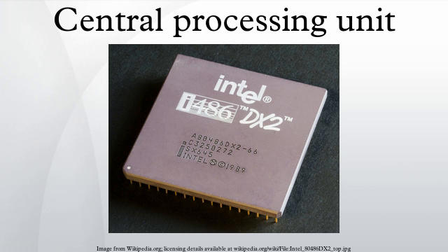In more complex CPUs than the one described here, multiple instructions can be fetched, decoded, and executed simultaneously. This section describes what is generally referred to as the classic RISC pipeline, which in fact is quite common among the simple CPUs used in many electronic devices. It largely ignores the important role of CPU cache, and therefore the access stage of the pipeline.